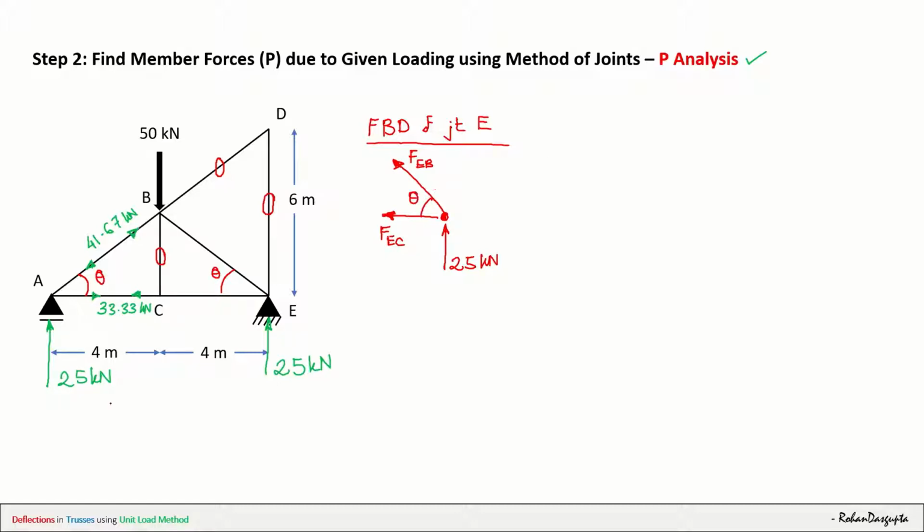So therefore, I will have to resolve FEB in the vertical direction and horizontal direction. So in the vertical direction, it will be FEB sine theta. And in the horizontal direction, it will be FEB cos theta.